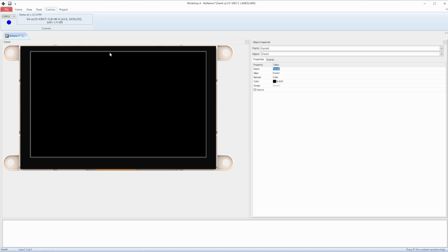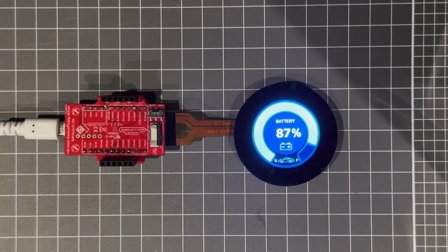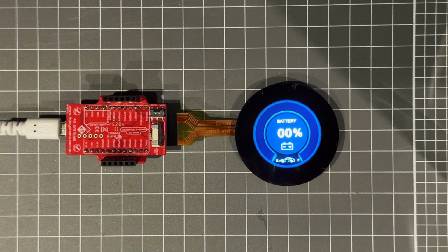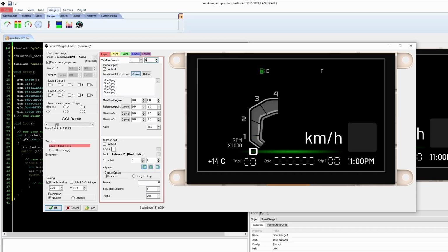First, let's quickly clarify what a PmmC actually is. The PmmC, or Personality Module Microcode, is the low-level firmware that runs underneath your application. It is not your project. It's the firmware that controls how the processor itself behaves. If it's outdated, certain features might not work properly, and Workshop will warn you about it.